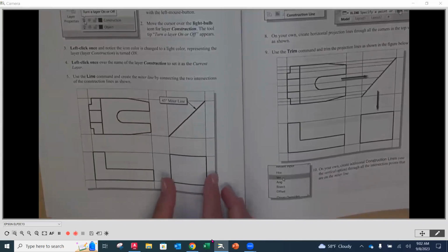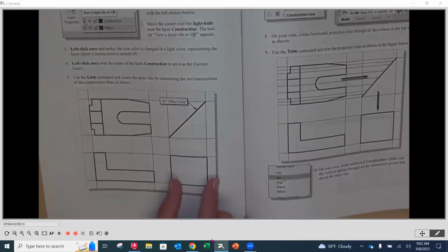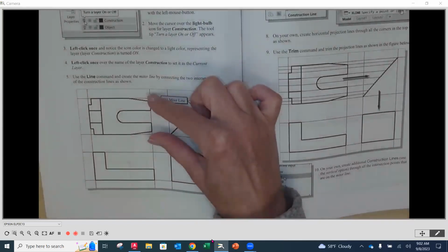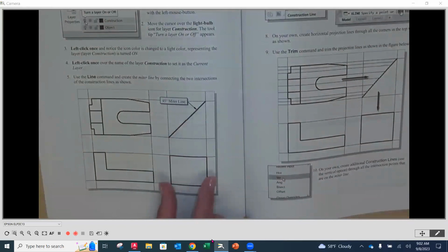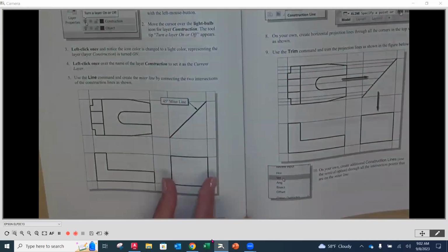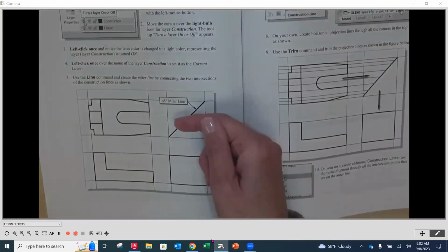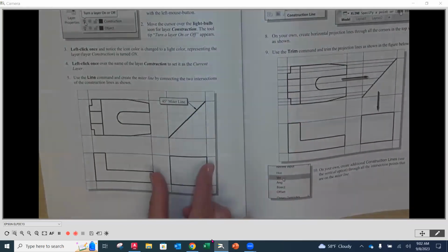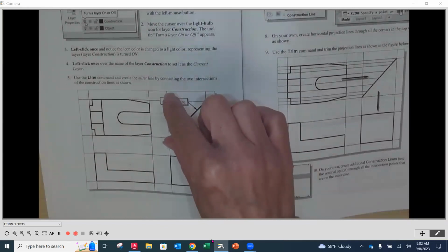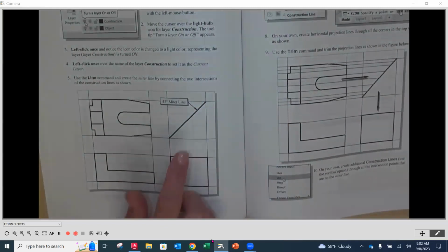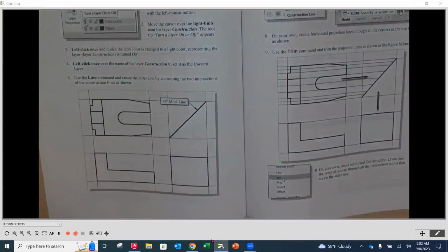Now, remember when we were looking at where we get our principal dimensions from. Our width dimension here in our right side view is the same width dimension that we see here, or the depth, right? So these two are related, and we could actually take this view and turn it, and we would be looking at the same right side view, but it would be turned, as you can imagine. But instead of doing that, we want to stick with our right side view.